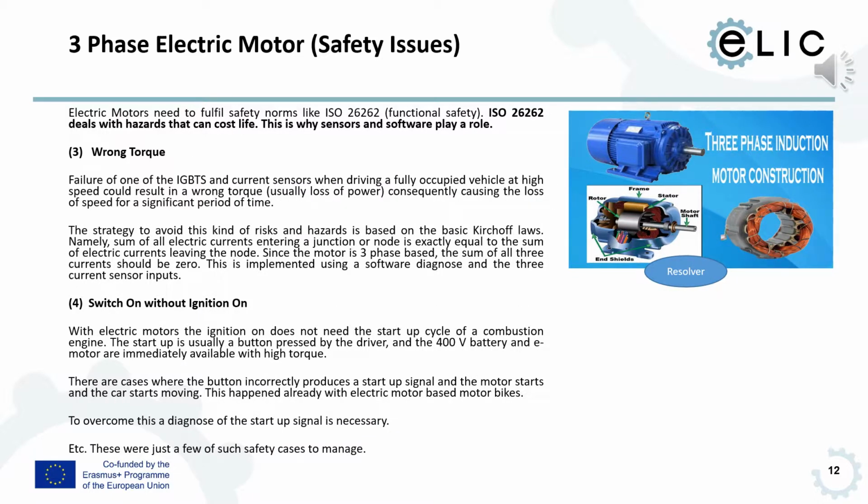Another safety case is that the currents with which you control the e-motor are not properly working, which means we have learned before that we use the Kirchhoff law to check the phase currents and if they are correct. And let's say we would not control that and would not find it out and continue driving, this would lead to a loss of power produced by the e-motor.